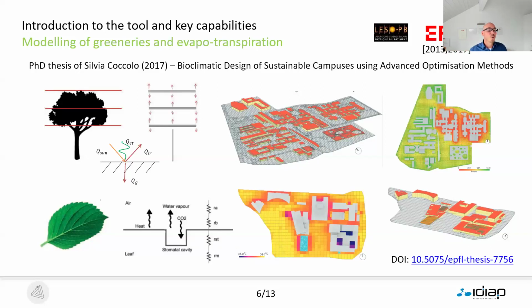So here, what we also, additionally to the greeneries and trees simulation, we also added the possibility to simulate virtual pedestrians. So we added the equivalent of small buildings in the scene that should maintain a certain temperature between 35 and 37 degrees internally, with different layers of the fat, of the skin, etc. And with those small buildings that were pedestrian-like, let's say, we could compute the mean radiant temperature, and we could compute basically two comfort indices.